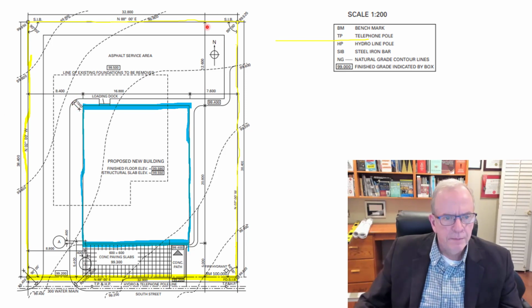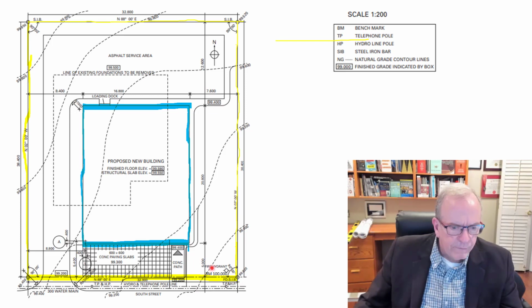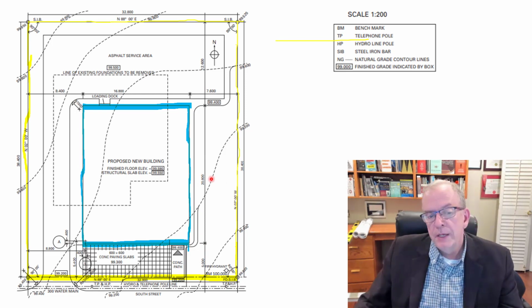Here's your rear setback line flowing through. Well, that looks like it's exactly in alignment with the building here. I would check that because it's easy to check. Here you've got 5,000, right? So 5,000 from the front property line. The building is 20.8 meters. 20.8 meters means it's 20,800 millimeters, right? So that's very easy, again, to check.